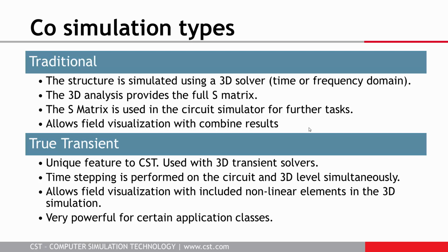But what I have used to visualize the time domain currents is the so-called true transient simulation. The true transient simulation is pretty special. It's a very unique feature that, as far as I know, only CST can offer, and it works only together with a transient solver. What is happening in the true transient simulation is that you do the time stepping at the circuit and the 3D level simultaneously. So it's like putting all the elements that are defined on the circuit really into the 3D model.